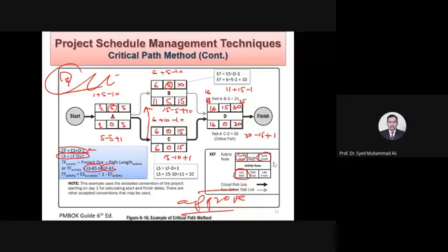In real execution, due to certain problems, the electrician could not finish. You started the work on the 11th day instead of the 6th day, but due to certain reasons you could not finish it in 5 days, because the pipes which were to be embedded in the concrete slab were delayed by 1 day. So the entire process got delayed by 1 day, and your critical path jumped in the real execution to this one. But that is the execution phase, not the planning. We are more concerned right now with planning.